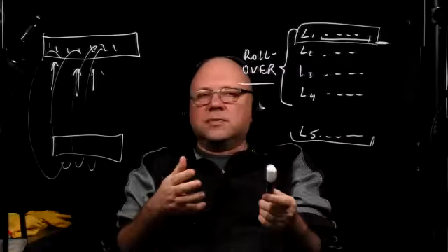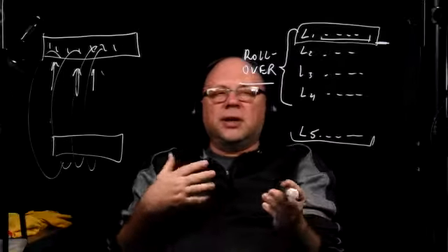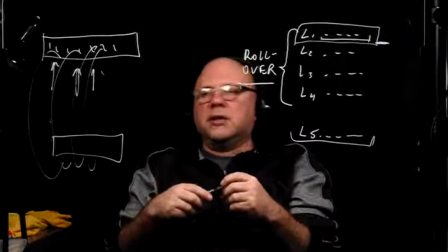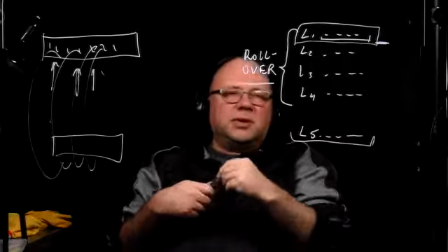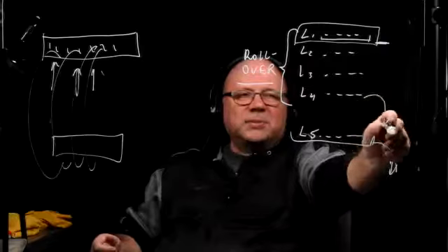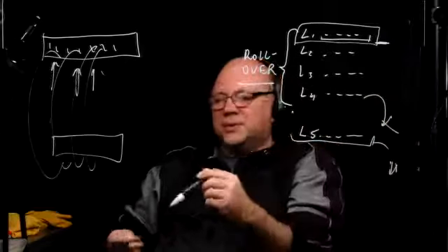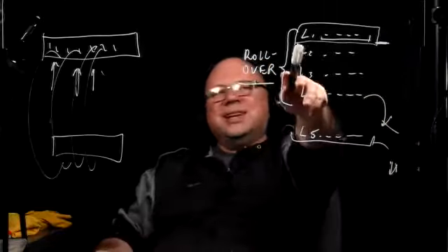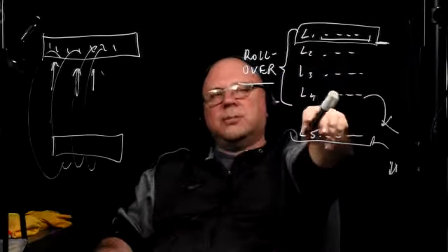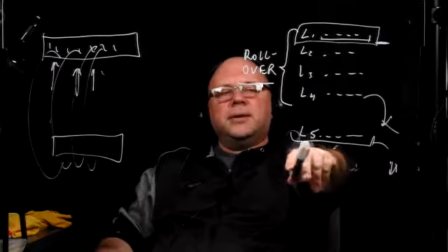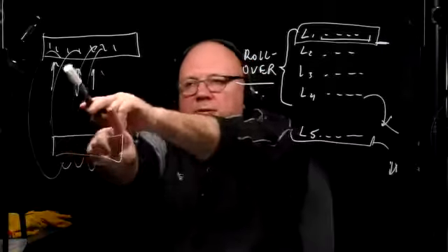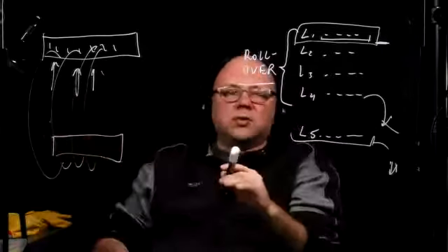So after a short conversation, they will be saying, okay, clients are complaining that when they call our number, they're getting a fax machine, because instead of that line, maybe this one will be connected to the fax machine. And then I would have to trace all those POTS lines, find out what their individual numbers are, and then I'll just have to rearrange those wires so the termination is done correctly.